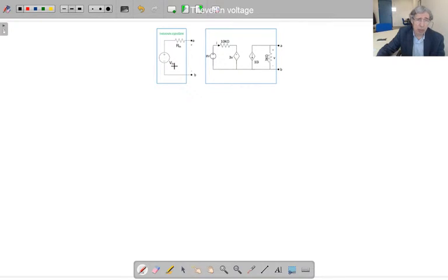The first step is finding Vth, and this video tells us how we calculate that Vth once the circuit is given to you. So we don't have to memorize anything. Just by looking at the circuit, we can find out the rule that we should follow. The rule is this: if we keep these terminals open circuit, that means no current here. No current means open circuit.